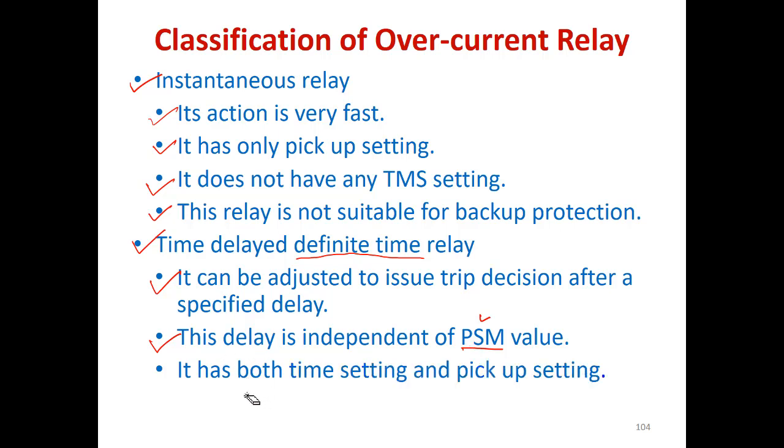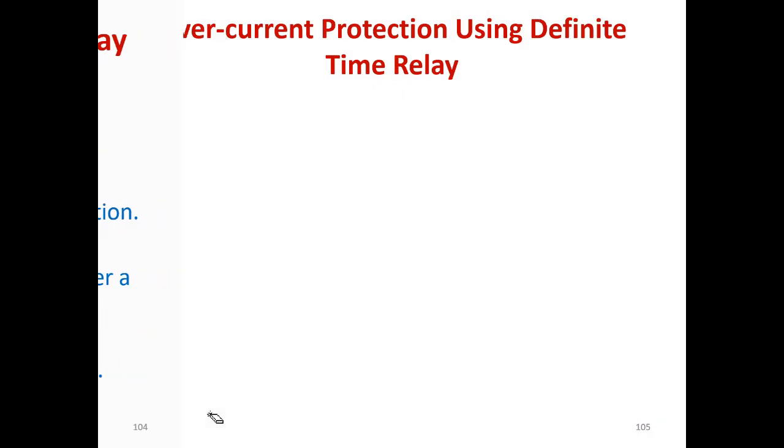It has both the time setting and the pickup setting. For the pickup setting, we give whatever value we want, and whatever time setting we give, it is fixed. It will not change based on the current value. So it is used for short length feeders generally. It is not used for long length feeders.